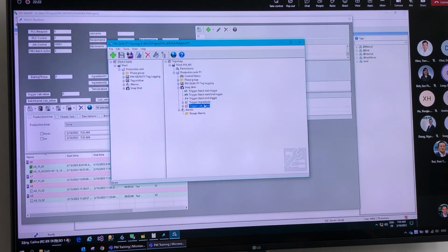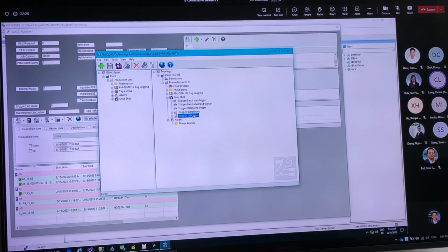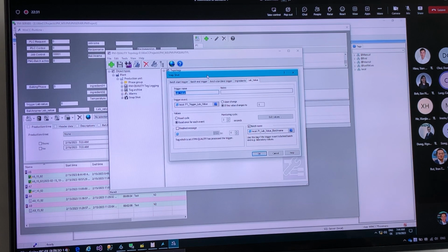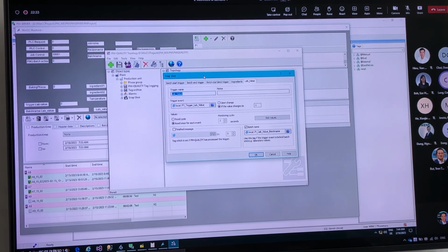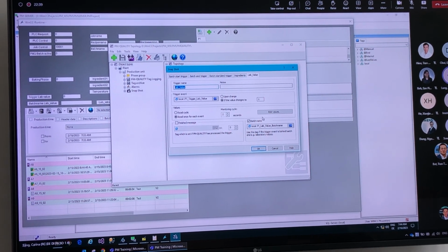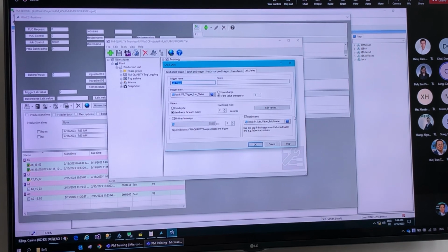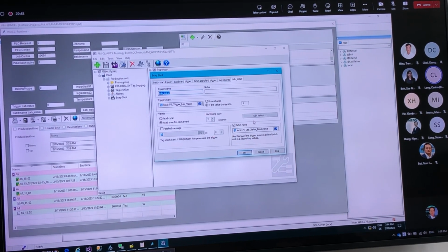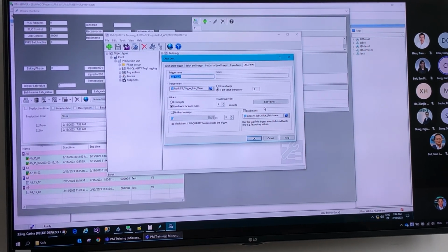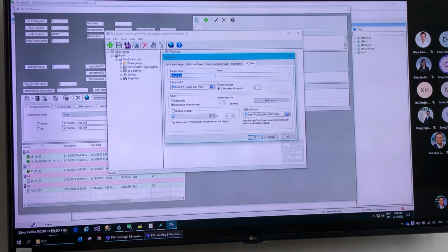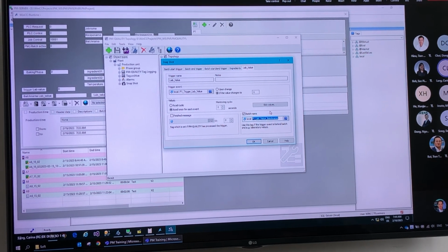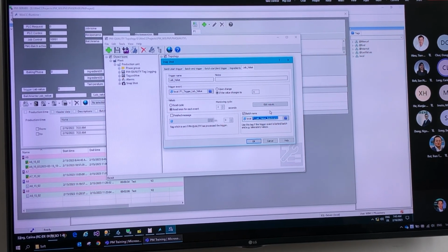And for that, we have added a new snapshot group or a new trigger to the topology. And if we open that one, we can see that the configuration of this snapshot is a little bit different than what we have done for the ingredients. As we can see, we have enabled the batch name here. That means we can give the information to which batch we want to add this data we have configured here in this group. And that means if we insert a batch name inside of this tag here, while another batch is running, we can decide to which batch we want to add the data to.